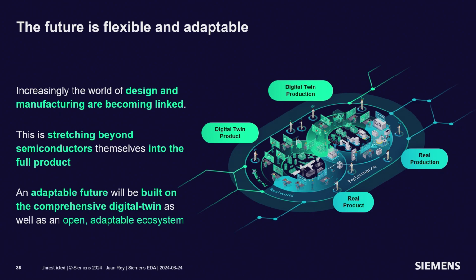It needs to support embedding passive devices and active devices in the substrate. So think about that. We need to work now with larger scales, with much more aggressive densities, and all that they are promoting the creation and supporting the funding for silicon substrates, for glass substrates, for organic substrates, and other more exotic things like even metallic substrates with other characteristics. So all that is coming, all that has an impact in the industry.